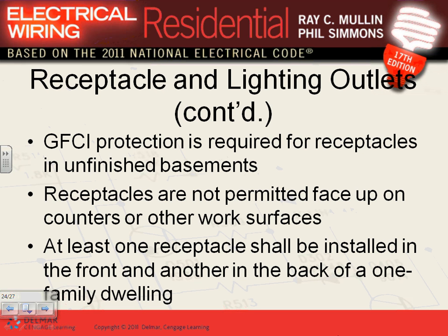Unfinished basement, all the receptacles, unfinished basement, outdoor, and in the garage or crawl space have to be GFCI. Everybody knows that? All have to be GFCI. In the bathroom, countertop kitchen, wet bar, unfinished basement, outdoor, garage, all have to be GFCI. And all the receptacles by code have to be two things. They have to be tamper-resistant. Everybody knows all the receptacles by code right now have to be tamper-resistant everywhere. Tamper-resistant receptacles cost $1.30 versus 33 cents.